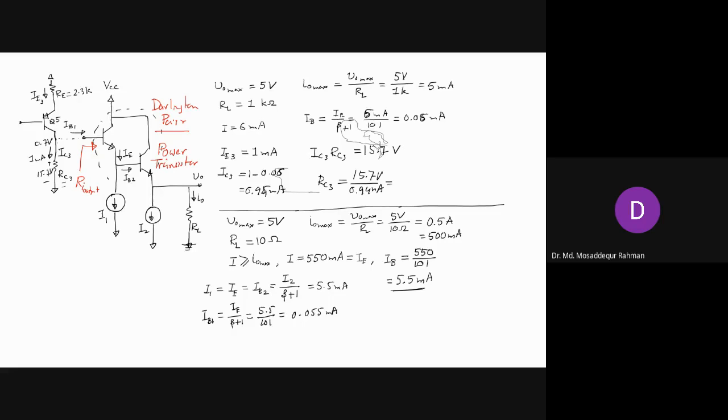You have to notice these differences between the requirements of the different circuit components at the output stage and the stages that you have before. Because the current here is only milliampere, you can use regular transistors, but at the output stage the current is in the range of ampere, or hundreds of milliampere. So a regular transistor will not work, right?